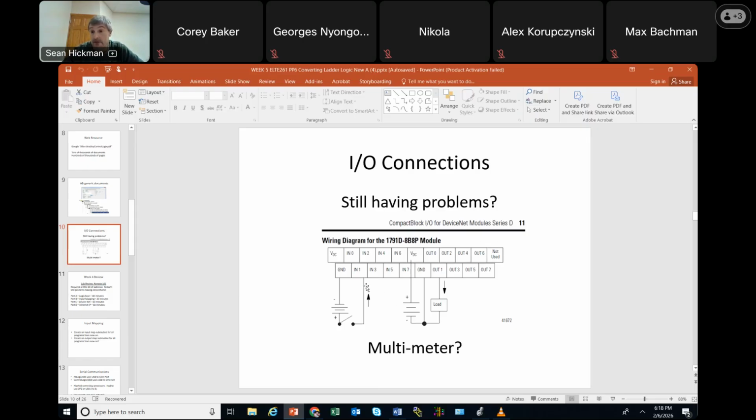But people aren't reading this, and they're jumping the voltage here and jumping the voltage here, and then what you're doing is you're shorting out the IO block. Now we're fortunate because the DC on your trainer is just a small DC power supply, and so it's got a thermal protection in it, and it shuts down the DC on that trainer, which means it shuts down your managed switch. So the trainer's still on, but you don't realize that the DC went down, your IO block's down, your switch is down, and all of a sudden you spend like half an hour trying to get communications again.